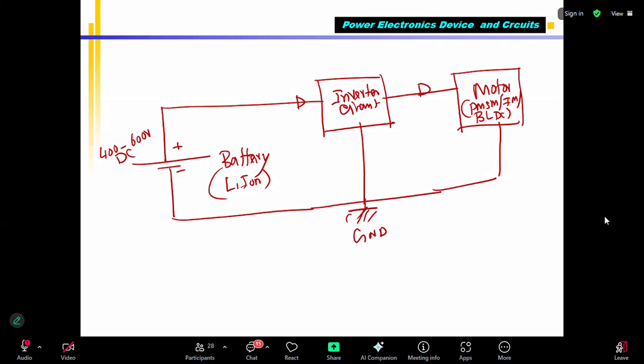This voltage will be driving the motor. This voltage is AC voltage, because it is not going to stay constant like the battery. So the battery supplied voltage should be converted into a sine wave, trapezoidal wave or a square wave.